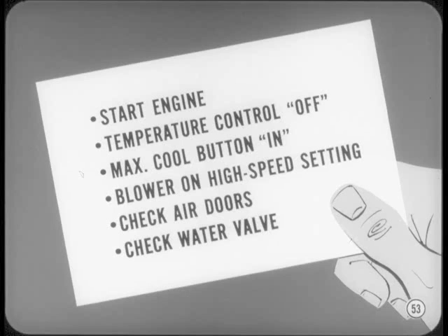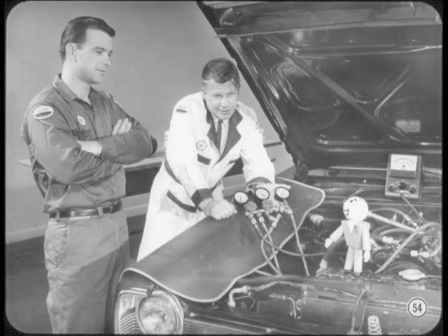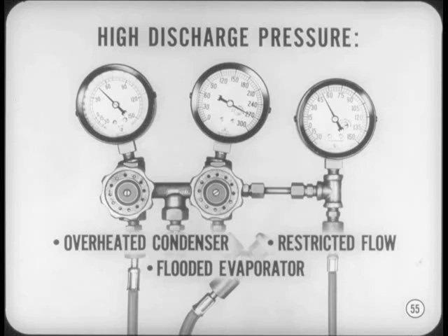While the system is warming up, you can check the air doors and the water valve as described in your service manual. When the system is warmed up, you can make a preliminary pressure check before making the tests given in the service manual. This quick check helps you narrow down possible trouble sources, but does not replace the service manual tests. Tell them what to look for, Fred.